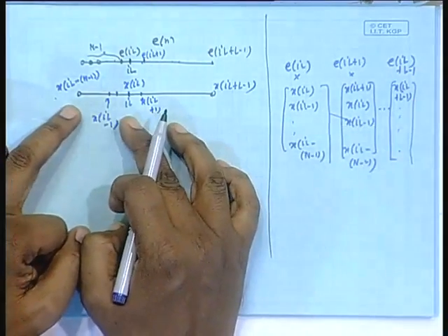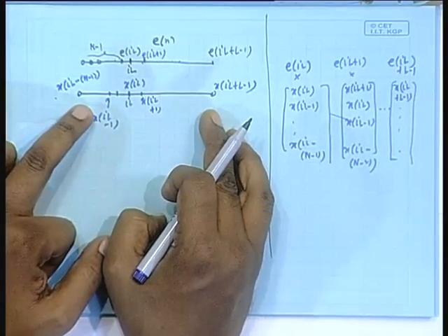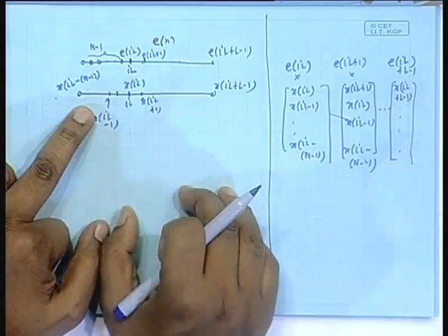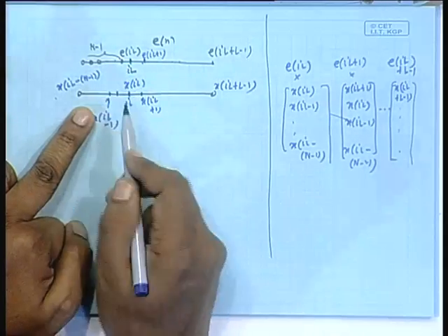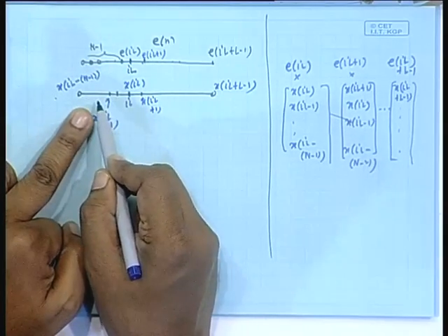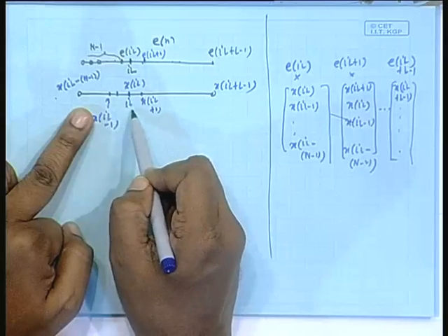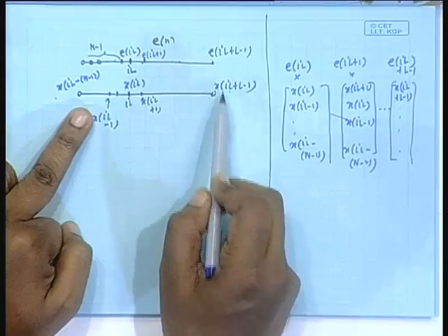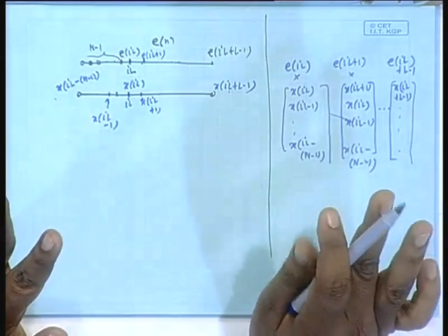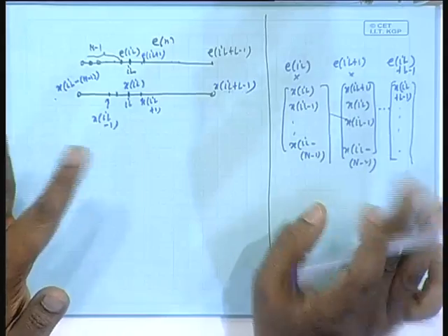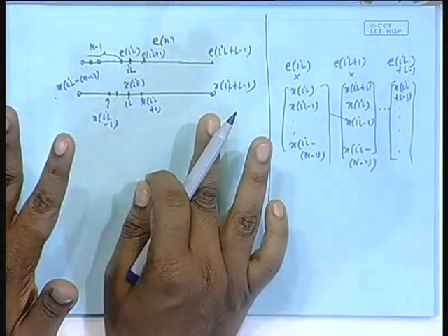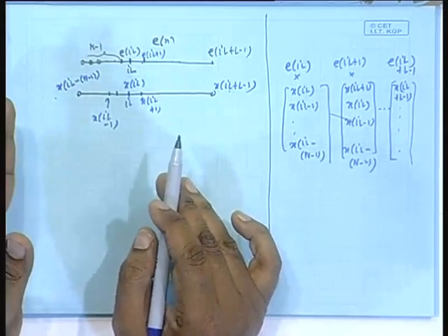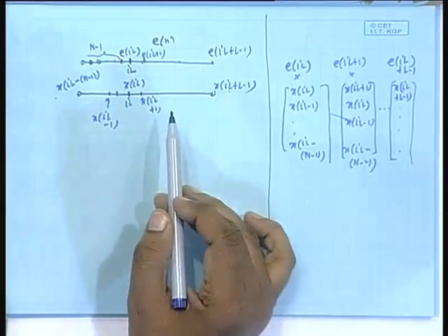Then if I shift this to the right by 1 and let any garbage come from behind, and again do sample wise multiplication, these zeros will take care of the same portion of n minus 1 length data. E_iL will multiply X_iL-1, isn't it? And this guy will go out, next fellow will come. So, I will get the second entry, isn't it? Second entry, then I shift it further again, let any garbage come. So, I will go on shifting how many times? Just n times. 0 shift, 1 shift up to n minus 1 shift.